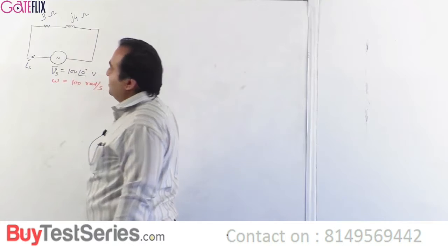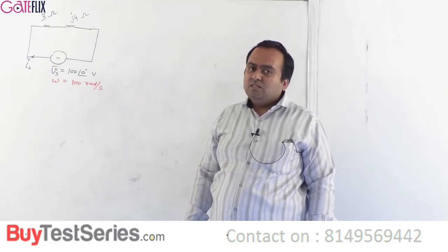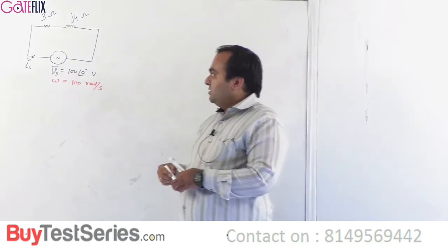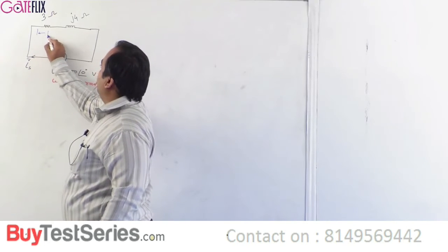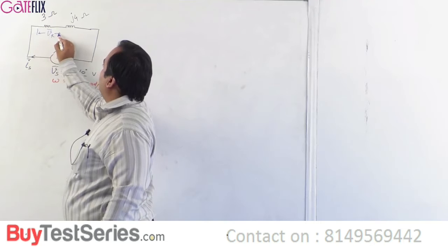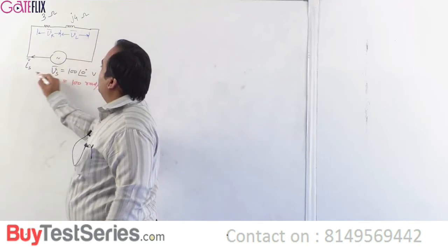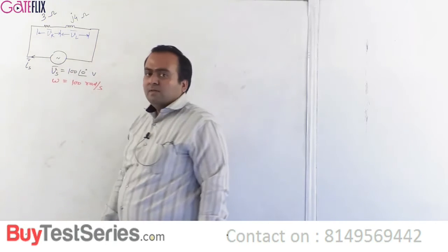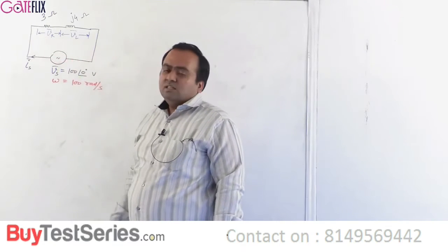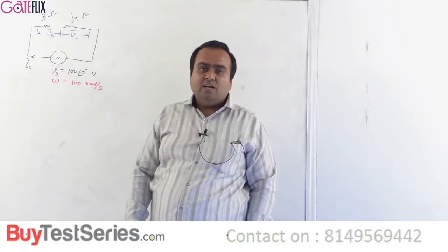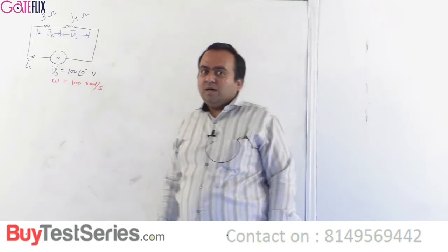J4 ohms, right? So 0.04 Henry can be replaced by J4 ohms in the circuit. Now what are the phasors that we shall indicate? This is VR, voltage across the resistance, voltage across the inductance, the source current, the source voltage. So source voltage, source current, resistance voltage, resistance current, these four are the phasors that we shall calculate, and with the help of these phasors we shall calculate very many things for this numerical.